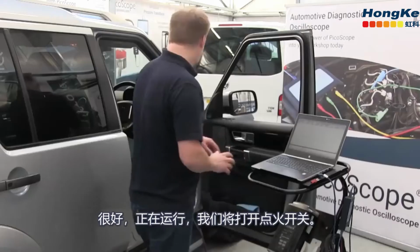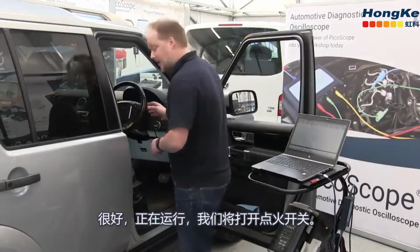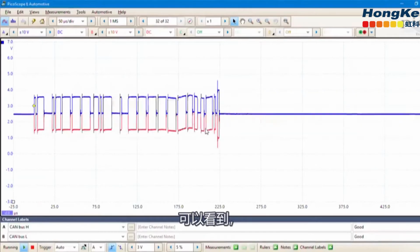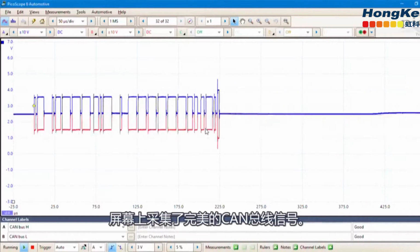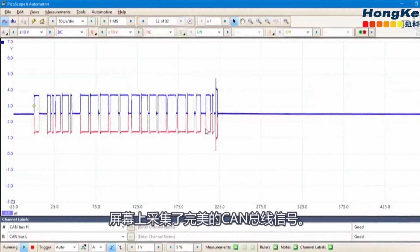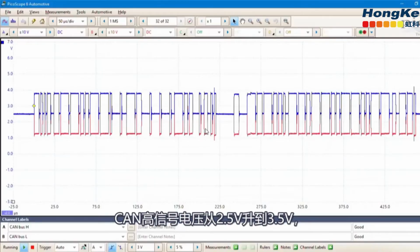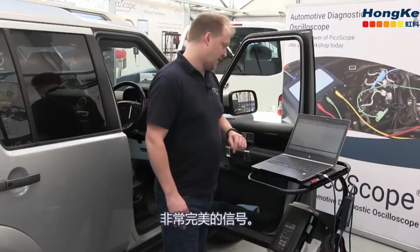Lovely, that's running, and we'll turn on the ignition. And there we go, lovely. We've got a perfect CAN bus signal on the screen. So we've got CAN high going from 2.5 volts up to 3.5 volts, and CAN low going from 2.5 volts down to 1.5 volts. Perfect.